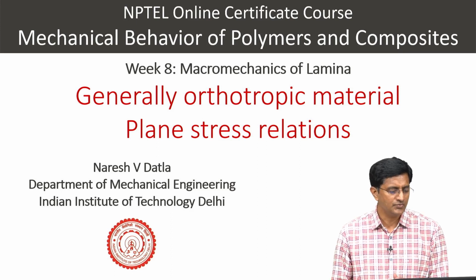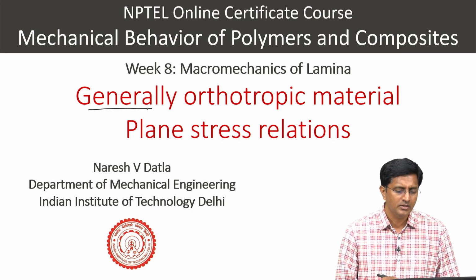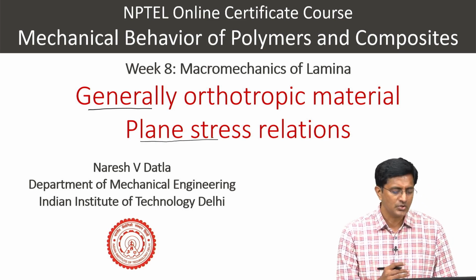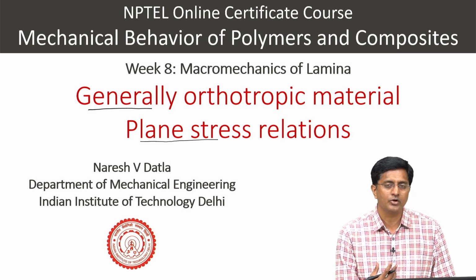Hello all. In this video we will be looking at the generally orthotropic material, and since we are looking at a laminar level, we can safely assume it to be under plane stress. So, for a generally orthotropic material we will show the relations between the stress and strain.